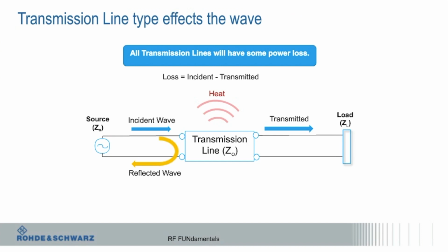People like to use lots of adapters and things, and you have to use what you have to use depending on the instrument. But realize every time you put a connection in there, you're degrading the standing wave ratio of your device, so you're going to get more reflections. I've seen stuff where they have like 6 things all bunched together, and if you looked at that on a VNA, it looks horrible, right? And you can't just cal it out. People like to think that, but it doesn't work that way.